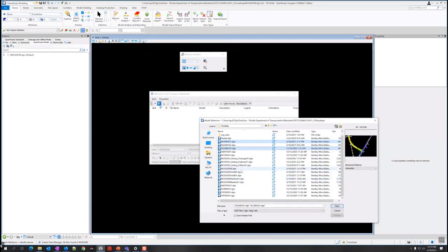Now for the detail modeling, I can attach it as long as I don't do live nesting from the main line to attach the detail in that one. The detail I can attach the mainline 61, and I'll need to for that one because I'll need to tie the two together. But when I run earthwork, I only want the detail attached, and for the mainline, again, I just want the mainline attached. So the transition one is a separate file, and that actually helps us out in this case.